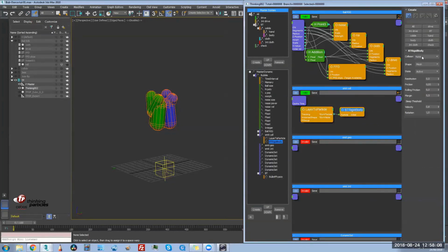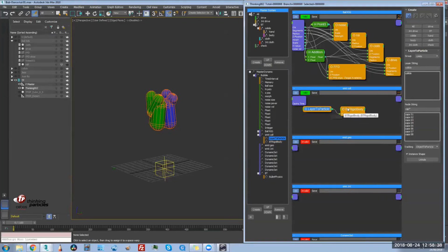So we jump back to our emit collider node, and now we can create some rigid body stuff. So we create the rigid body node, we assign the bullet engine, we check convex hull and kinematic. We use kinematic with 0 everything, but the margin we will set to 10. And it is important, that parameter, because that one specifies to the bullet engine a kind of envelope area around the surface where it should pay more attention to avoid mistakes, like interpenetrations or unwanted results.